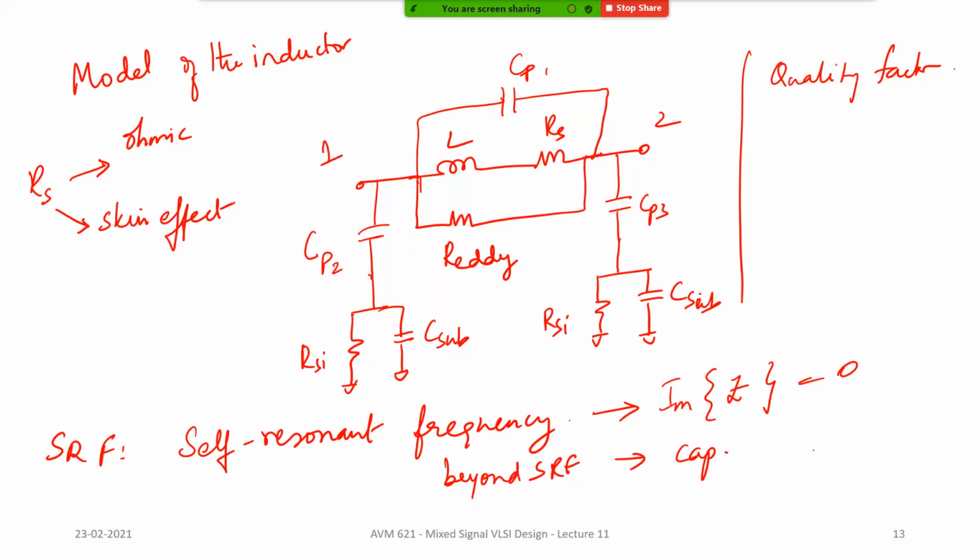In a metal, the high frequency signal actually goes through the surface. Correct. So if you see the profile of the high frequency current across the cross section of any conductor, the higher the frequency, the more the current tends to flow in the outer edge of the conductor.